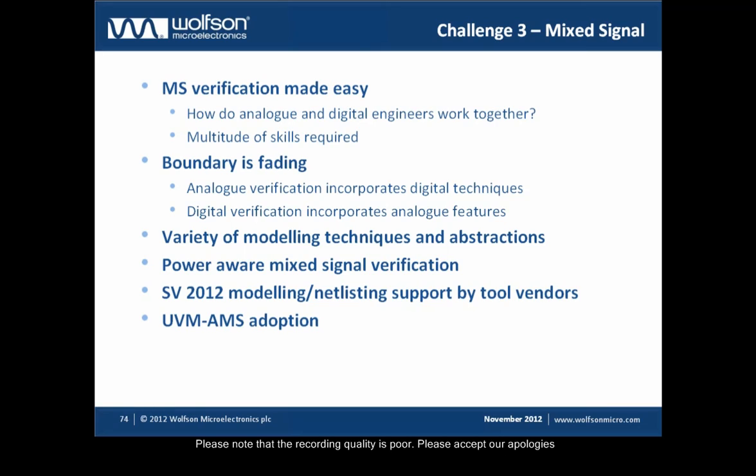Then you've got the added complexity of more power modes, which you want to apply to mixed signal verification as well. Also, this is a technique borrowed basically from the digital space, which now needs to be applied in the mixed signal space. So the upcoming SystemVerilog 2012, for example, includes features to model multi-value real nets. So you can actually model the voltage, current, and any kind of meta information in an event-driven environment. So will that be supported on emulation platforms? I don't know yet.